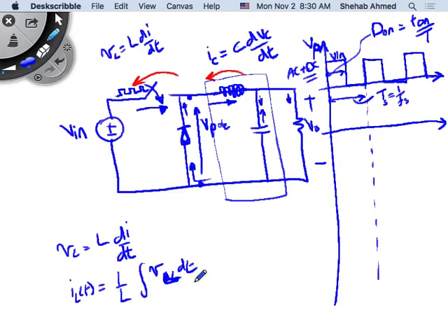Ideally, if the inductor is very large and there is an AC component, right? Or actually, if there is a DC component, if you're feeding this inductor, this circuit here, with a DC component, what will the inductor look like? A short circuit, right? How about if you have any AC component?